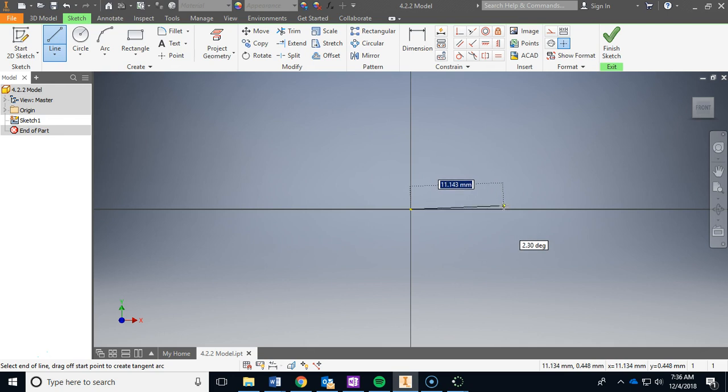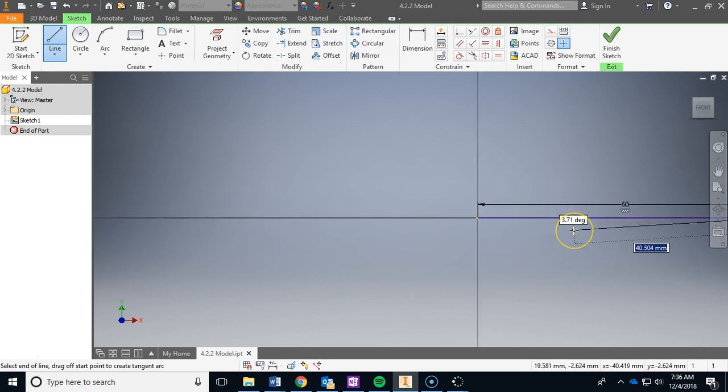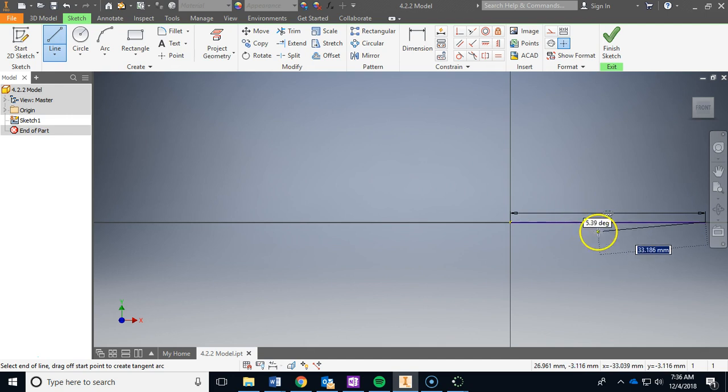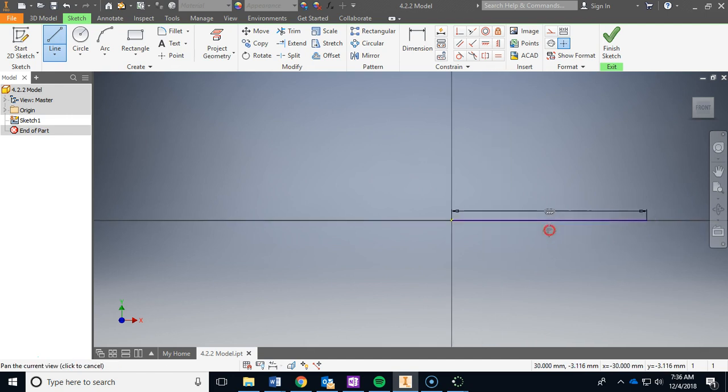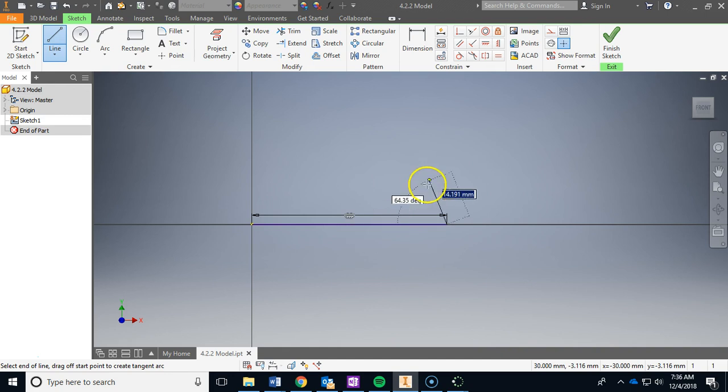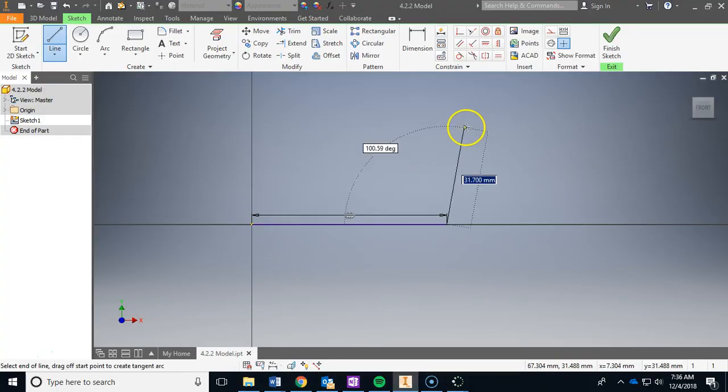If I move it on accident like that, your line's going to be incorrect. We said we're going to go 60 for the width. So 60. Now, remember to zoom out, you roll your wheel backwards. To pan, you left click, hold the wheel, and move the mouse. And what did we say we're going up? Anybody remember? What was it, 40? Yeah, we're going up 40.